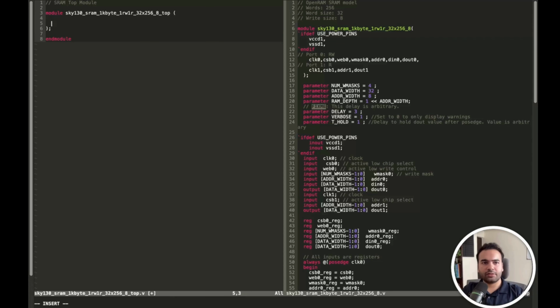All right. The first thing is the clock, and the next thing would be the SRAM signals. The first would be the SRAM chip select, so chip select underscore I. Similarly, we would have input wire SRAM write enable underscore I. The reason I want to do it this way is that I generally prefer active high signals over active low signals when writing test benches.